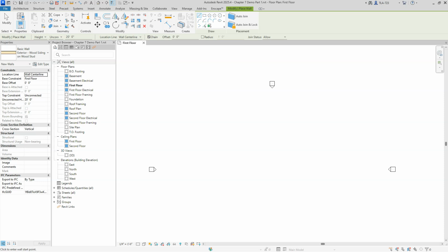All right, so next we're going to repeat something we did earlier on in the semester, and that is to import a CAD file into Revit. And basically what we're doing with this is we're just bringing in the lines that would represent the floor plan of the house. And then we're going to use that to trace so that we can create a 3-dimensional model over the top of it. So that house.dwg file that is attached to the assignment that I had you download, we're going to go ahead and import that next.